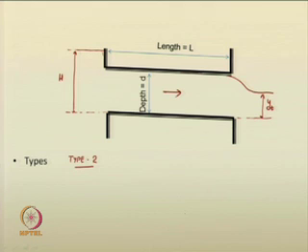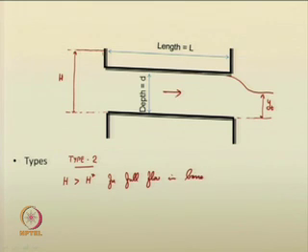What happens here is that H should be greater than H star for full flow. So, we are suggesting H is greater than H star. Your y t is less than the depth of the barrel. These two conditions will make the flow inside the barrel full flow itself. Here the culvert is hydraulically long.